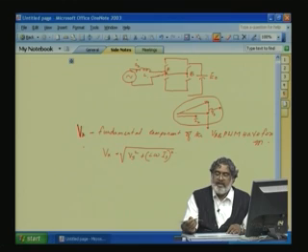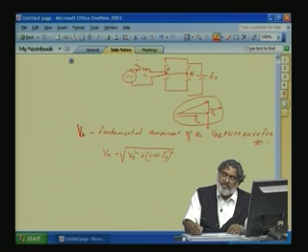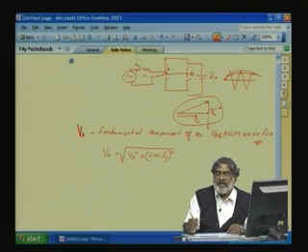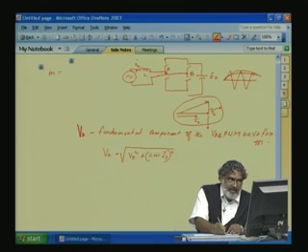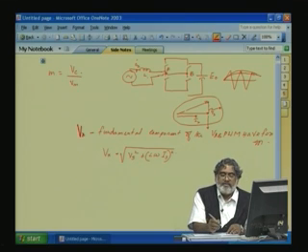But in all practical applications, we will not go to the extreme modulation. If you take a sine triangle like this, we will not go to this range. If you go there, the pulse would become very narrow and the system may not respond. So, we will always restrict the modulation index, that is the height of the sine wave. Modulation index MI is equal to VC by VM maximum value.